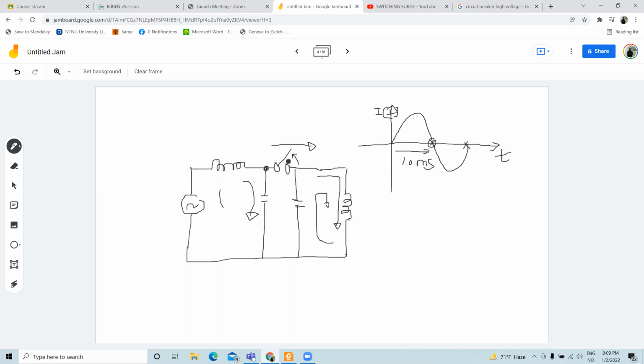Circuit breakers are normally designed to interrupt the current exactly at current zero crossing, because at that time you do not have any current flowing through the contacts. So circuit breakers interrupt the current here. But if the breaker is too good for what it needs, it will cool the arc even when a certain amount of current is still flowing through the line.